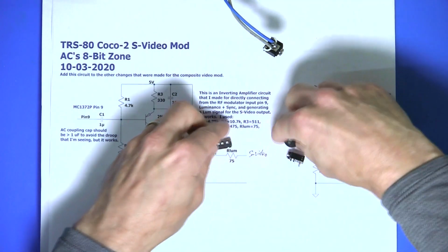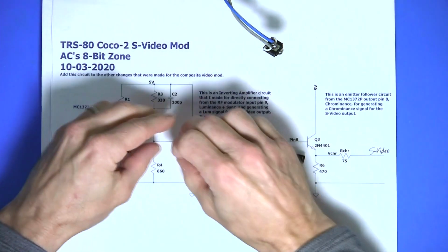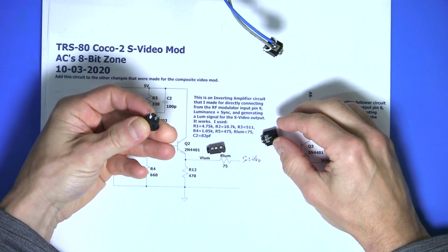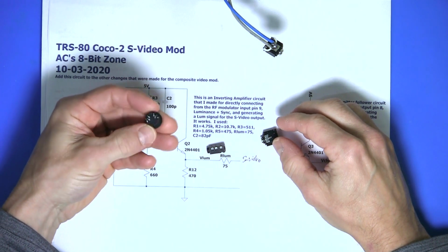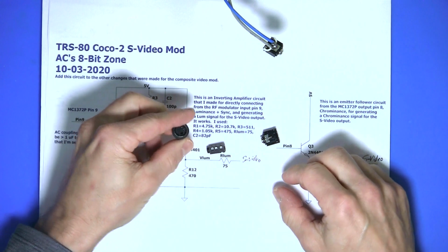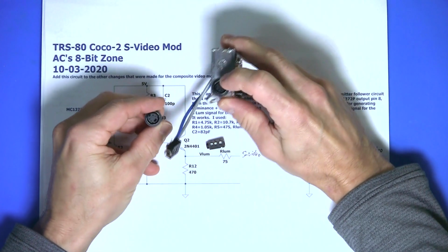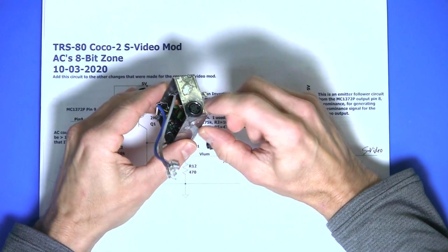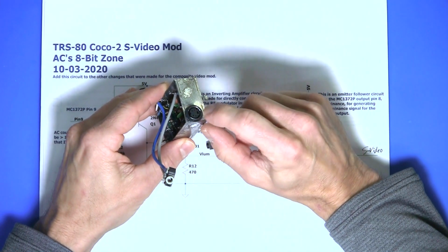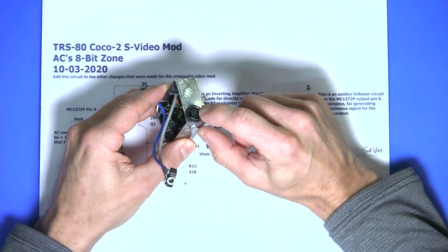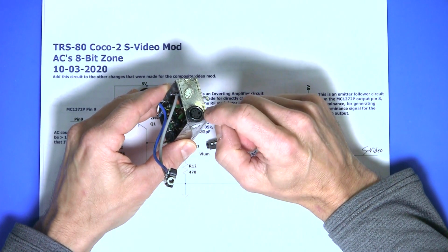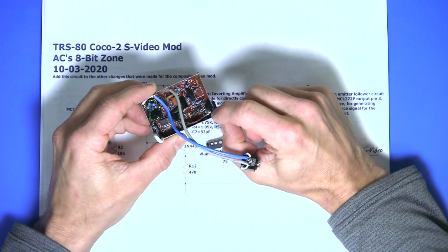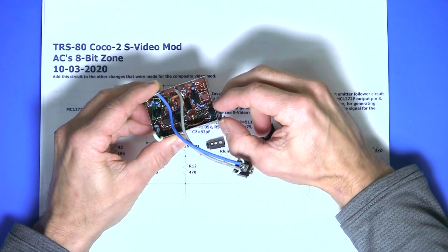Here are connectors, and I'll put links and part numbers to all of these. I think I purchased all of these on Amazon. Here's a PCB or board mountable or even panel mountable S-Video connector. That's what I installed here. First I desoldered the old RF output RCA jack off of there. I rounded out the opening to, I think it was 7/16, and I epoxied this connector in place so that it couldn't move.